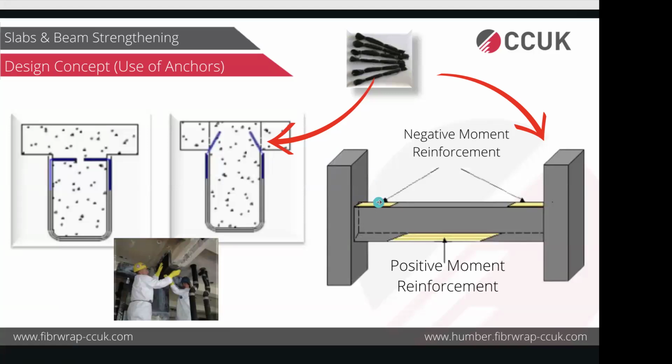In this as well, there is a common detailing mistake people make. What they do is they take the FRP up to the ends and support and stop it there. Now, as structural engineers, we know that if we are strengthening this for hogging moments, that's the location where we have the peak moment or peak stresses. If you curtail the reinforcement at the peak stress area, then there's no point in doing that strengthening, because you want some sort of development length or anchorage length beyond that point.